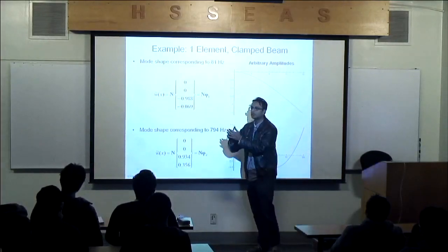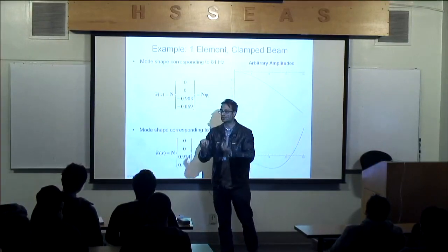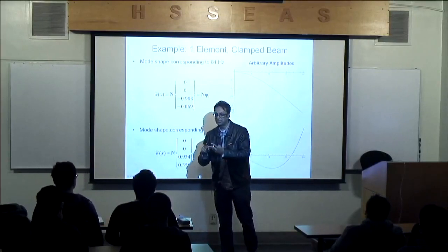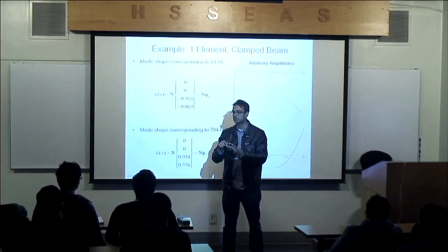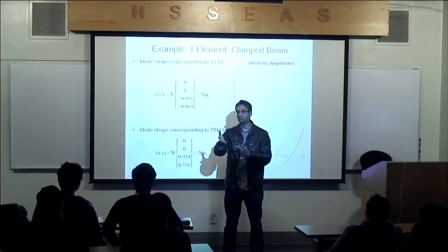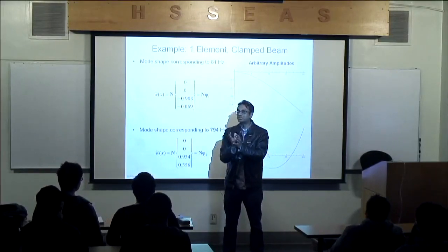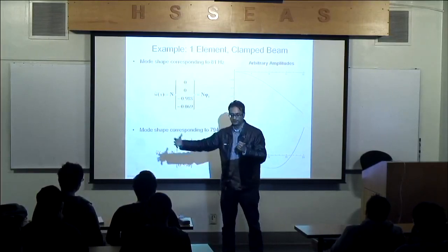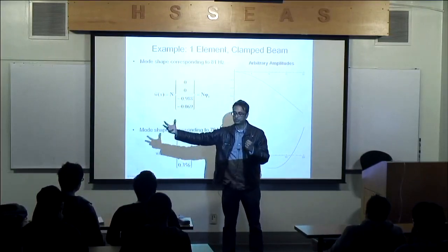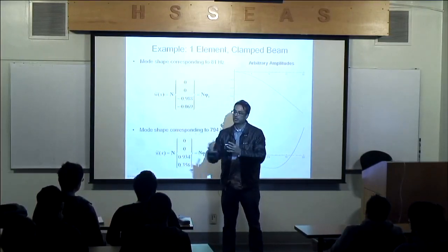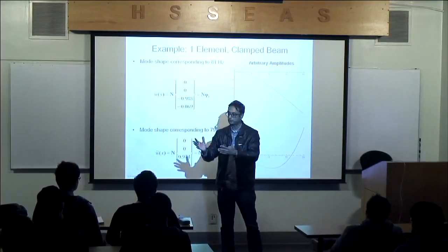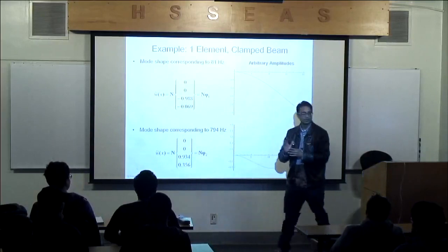It's the dynamic characteristic. It's the characteristics of the structure. The structure has two characteristics, the frequencies and the mode shapes that go along with them. So in the video I showed you at the beginning, the Tacoma Bridge, that bridge on its own has some fundamental frequencies and some fundamental shapes. The forcing function that came in, which could have been the wind or some other event, caused particular mode shapes to get excited. And that's why that bridge deformed the way it deformed. You follow? Yeah. Okay. Excellent.